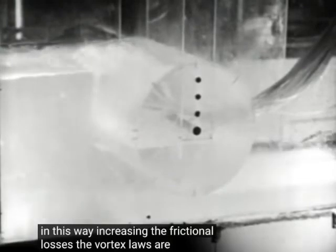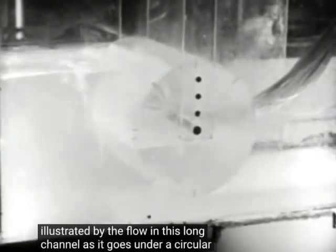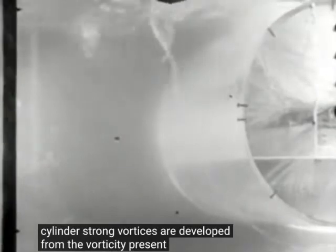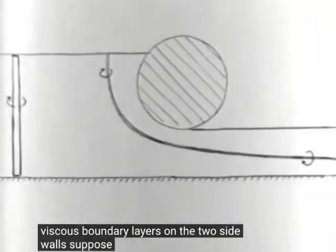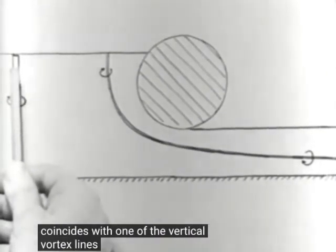The vortex laws are also illustrated by the flow in this long channel as it goes under a circular cylinder. Strong vortices are developed from the vorticity present in the viscous boundary layers on the two side walls. Suppose that this thread of fluid coincides with one of the vertical vortex lines.